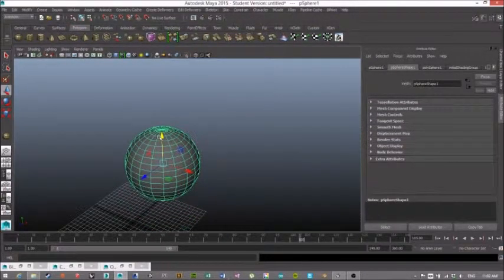So this is going to be really important if you want to cut plans or sections. It works the best with meshes. I'm sure most of you have NURB surfaces. That's fine. All you do is there's a nice little button in Rhino, convert poly surface to mesh. Just convert it to a mesh, join it all, dump it into Maya, you have a mesh to work with. They're just lighter.